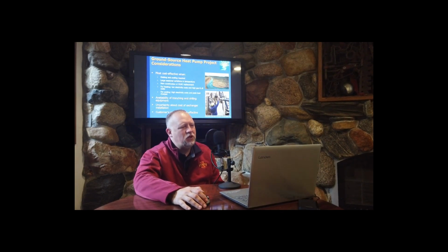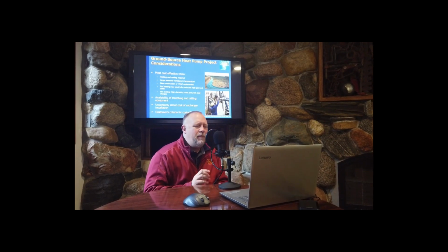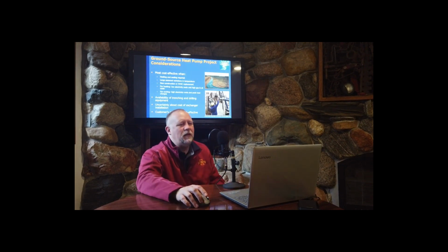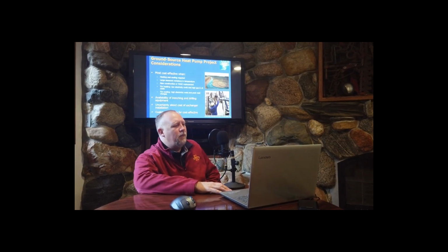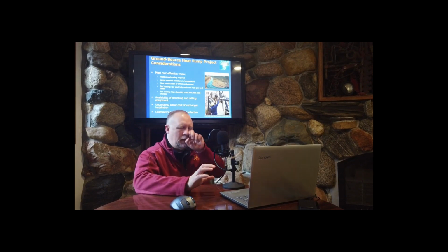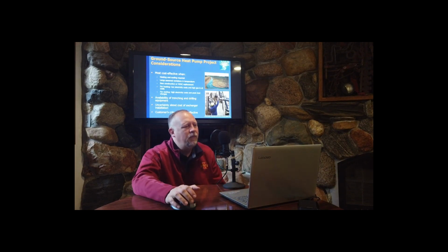The next couple pages are just showing the process of the drilling rig. Okay, most cost effective, and a heat pump is not always cost effective, to be perfectly honest. Sometimes it can be drastically expensive. It depends. Most cost effective when you have heating and cooling, and I'm going to say you have a pretty balanced load between heating and cooling. You have an even range of cooling and an even amount of time that you spend during the course of the year heating.